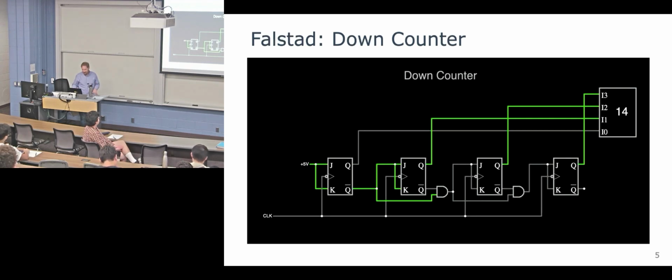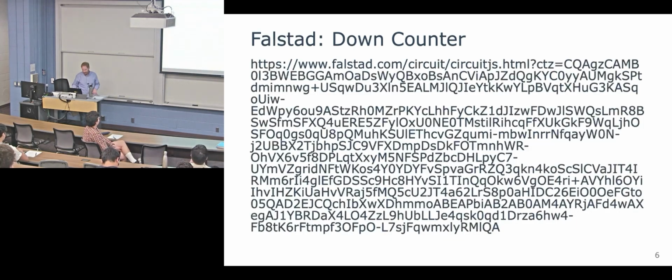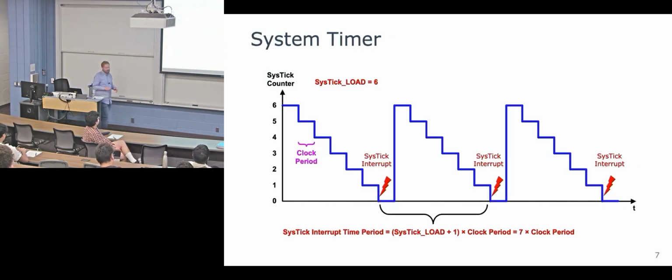So it doesn't take up a lot of processor space. Okay. So here you're going to set your reload value. In this case it's 6, and it's going to keep counting down, down, down. This will be able to set up your periods this way, and then SysTick will go off, and you can, again, have an interrupt as a result of that.